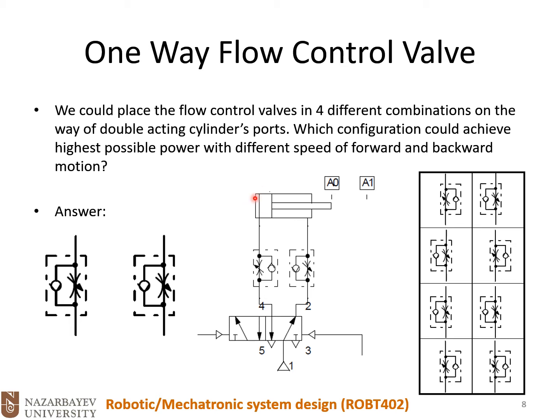So we have full power, full pressure and the maximum force here, so we could still move the maximum possible load with the air pressure of the compressor, but on the other side we have limited speed, and sometimes we don't want these pistons to move that fast freely, and the speed should be adjusted based on the application and the safety.